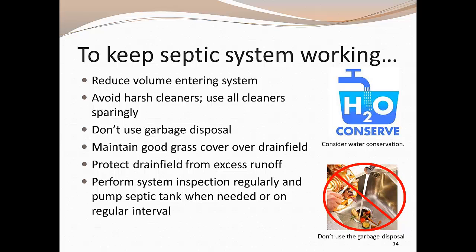To ensure your septic system continues to function properly, follow these good management practices. Practice water conservation through the use of low-flow toilets and shower heads, and match the volume of water used in the washer to the size of the laundry load. Avoid washing more than 2 to 3 loads of laundry per day, and only run the dishwasher when full. Avoid harsh cleaners and use all cleaners sparingly. Harsh chemicals can be harmful to the bacteria in the septic system. Avoid using the garbage disposal. Solids and grease from garbage disposals can clog the soil treatment area.